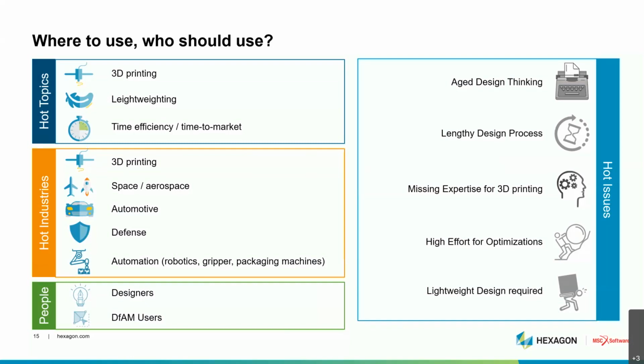As well, our software has different shape quality settings. So you can start with a preview setting. You can set up a model in 5 to 10 minutes, maybe not that detailed, so maybe just 2 or 5 minutes, just the most important load cases. And then say shape quality preview, and after 10 to 50 minutes, you see where the design could go to and how much weight can be saved and what could be a result.